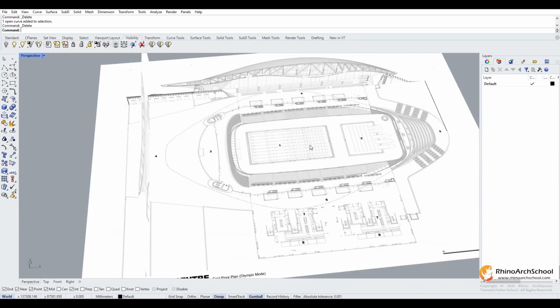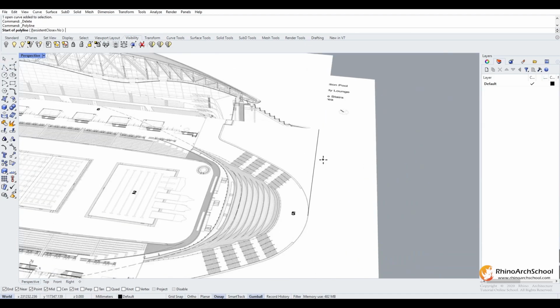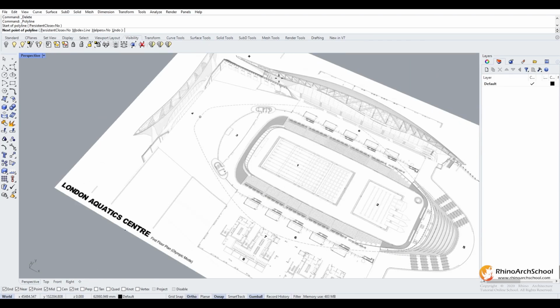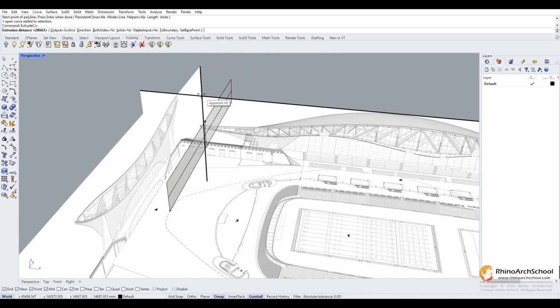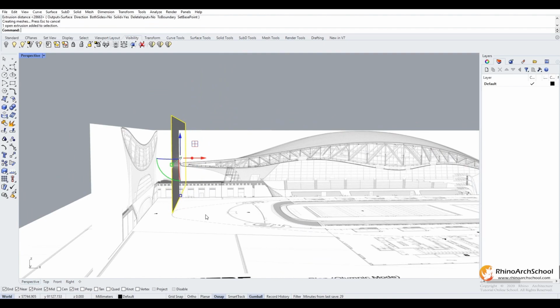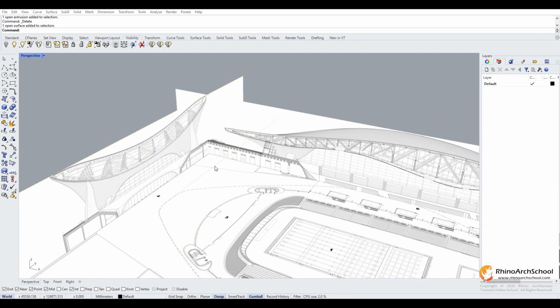To make sure you have aligned your building properly, you can use the line tool to create some references. We do that by simply making a line using Shift-Tab to create a straight line. Then we can extrude our curve. And you'll see that the section matches the plan. And you can do the same thing with the elevation